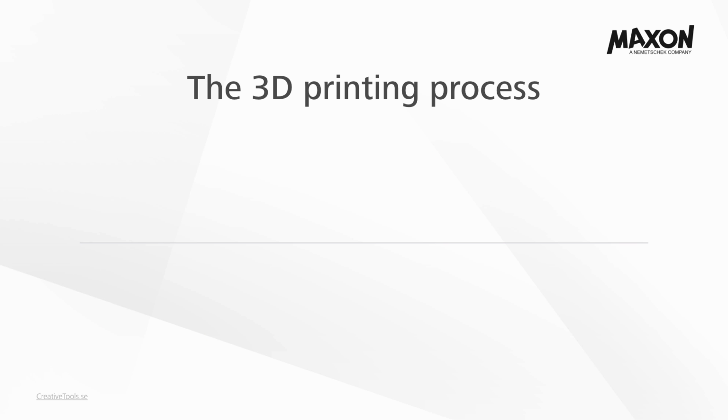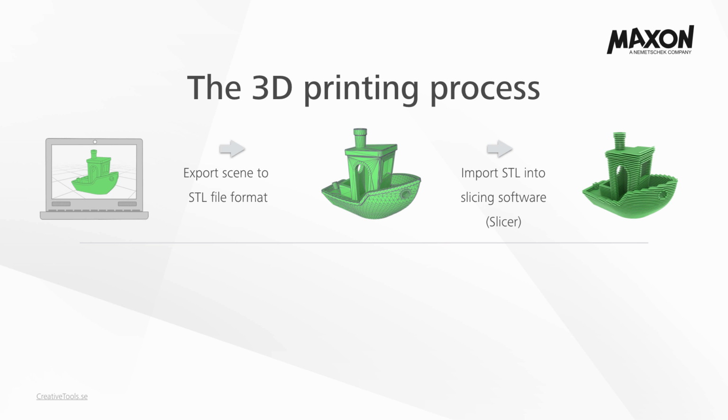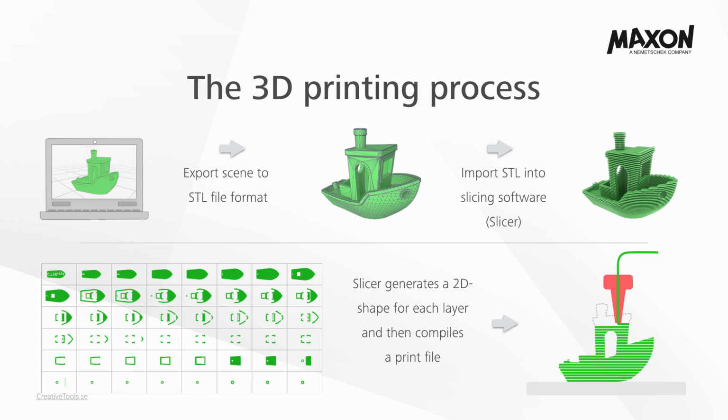In this slide, I would like to explain the basic anatomy of 3D printing, which is quite simple. First, you create a 3D model in Cinema 4D as usual, and then you export the object you want to print as an STL file. You then open the same file into a slicing software which usually comes with the 3D printer. The aim of this slicer is to literally slice the object along the z-axis and cut it into many thin layers. All layers have the same height and are described sequentially by the slicer as separate two-dimensional images. These are then compiled into a print file that instructs the printer to start making the object one layer at a time. This file can be sent to the printer via USB cable, Wi-Fi, or simply copied onto a flash drive, which is then inserted into the printer.